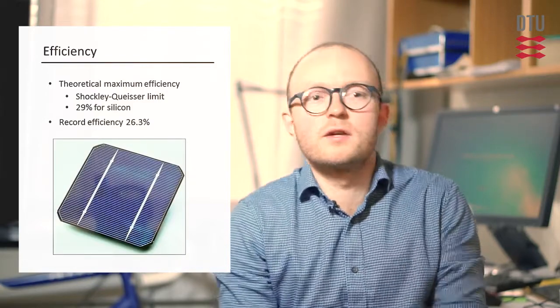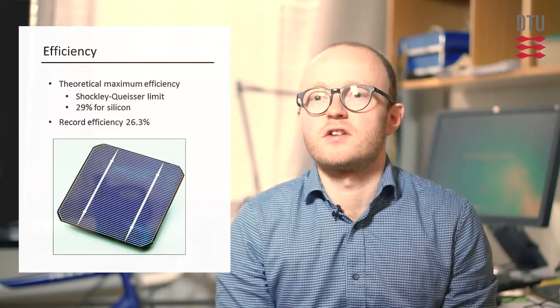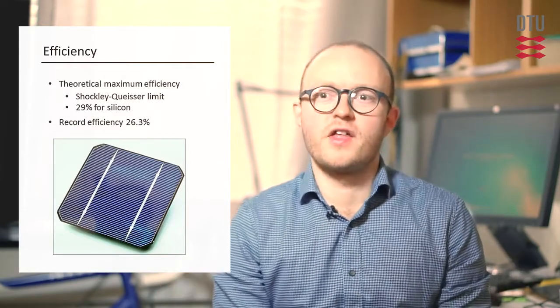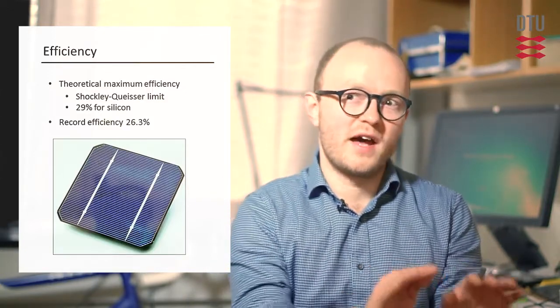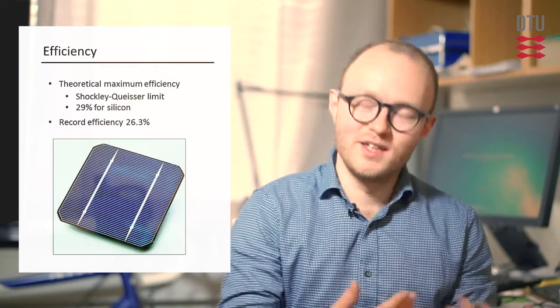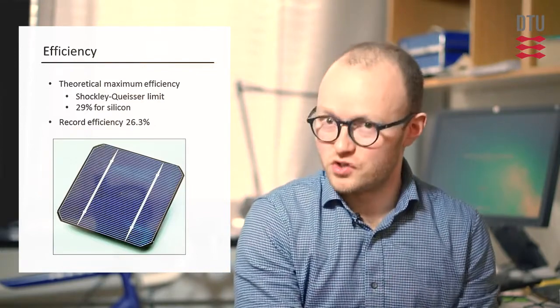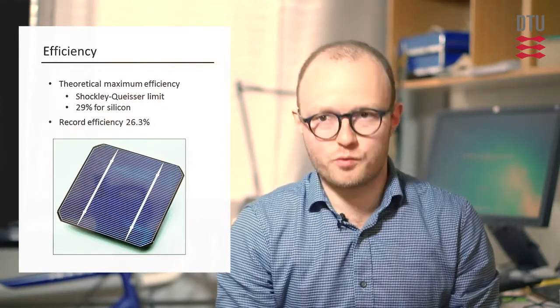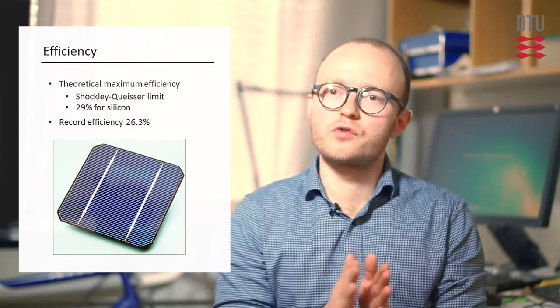And this is what we attempt to solve with the black silicon nanostructures, which make this reflection go away. But in order for that to result in a record efficiency, you also need to passivate the surface really, really well, in order not to lose the excess electrons that are being generated from this excess absorption.